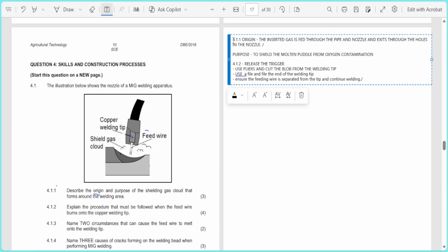This will prevent damaging the delicate copper tip. Yes, so this is very important because the filing also restores smooth wire passage, like clearing a blocked pipe. Skipping any of these steps that are listed here can lead to inconsistent welding and can also damage the equipment. So make sure you keep some spare tips handy for quick changes during a welding job.